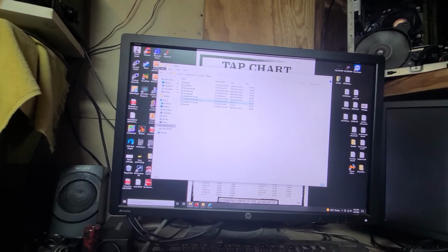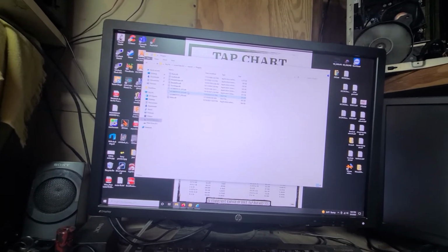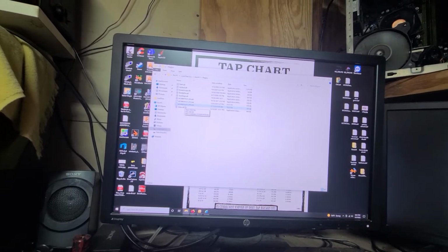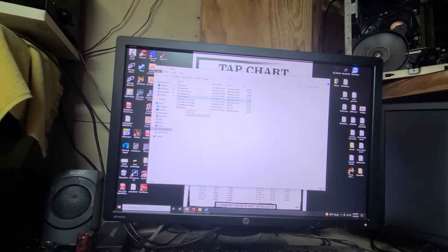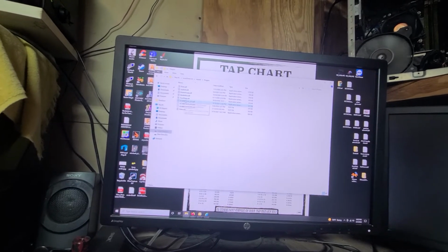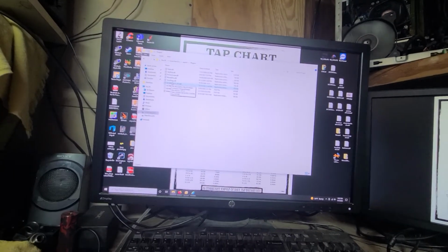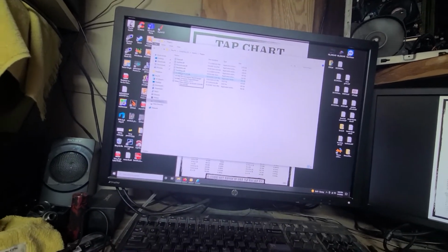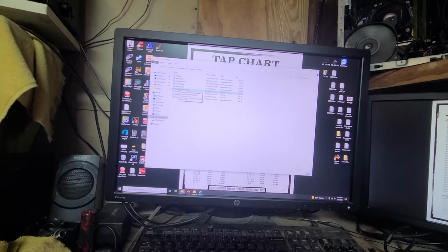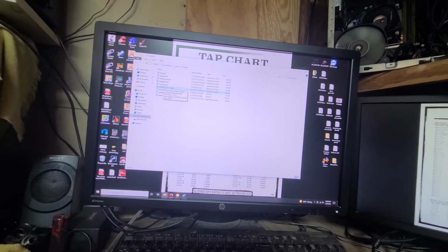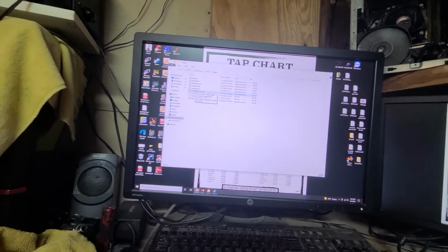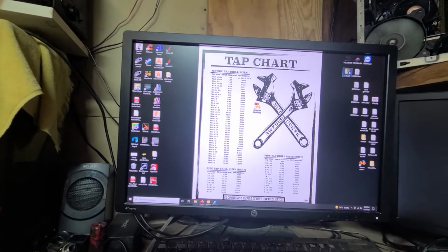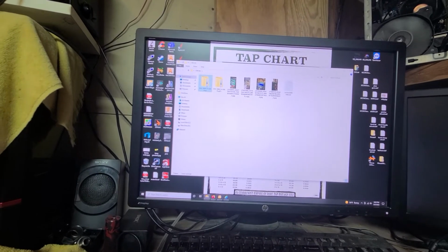Also, the automatic installer will throw a couple of different DLL files in here, so you want to go in here and delete them and make sure that you only have the one that pertains to the hardware that you have. So you can have the UC100, you can have the UC300 USB, you can have the UC300 Ethernet, and so forth. But let's say, for example, that you're dealing with one of these China machines,